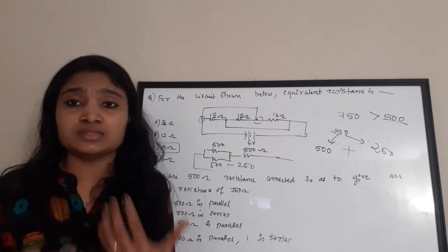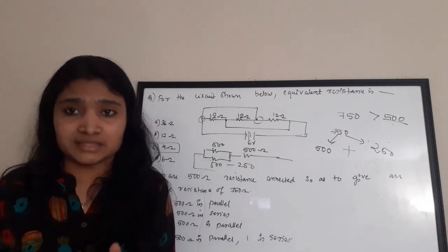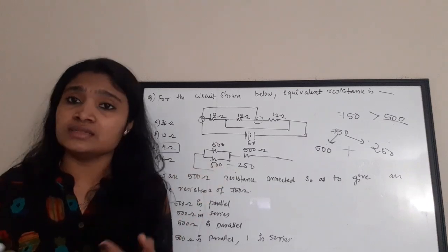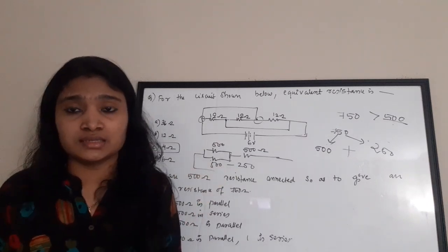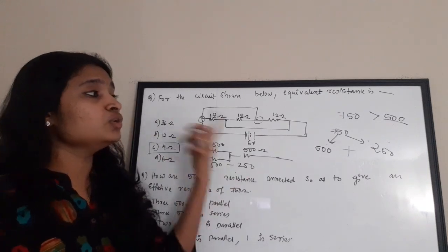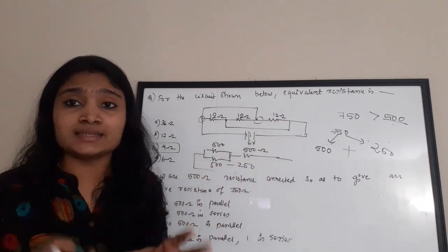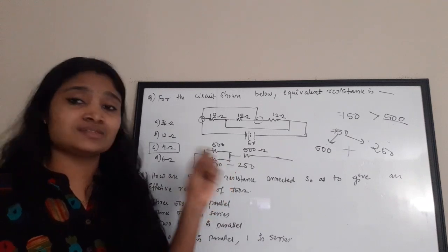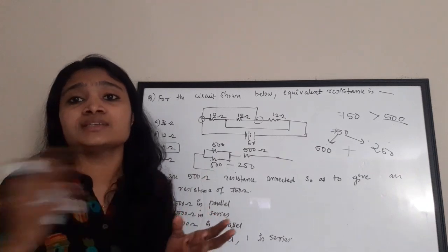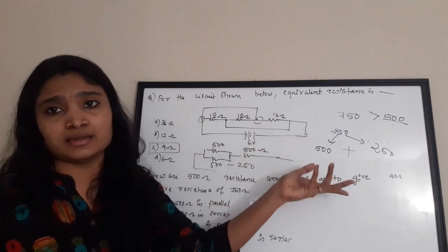Always keep this in mind: if you want to get an effective value which is greater than the present value of the resistors you have in your hand, it will be a series combination of those resistors. Now look at the value to be obtained as effective. Can you split it as divisions of your resistor value, or as a combination of the resistor value plus some other value? If you can, you can form a combination of series plus parallel maybe.